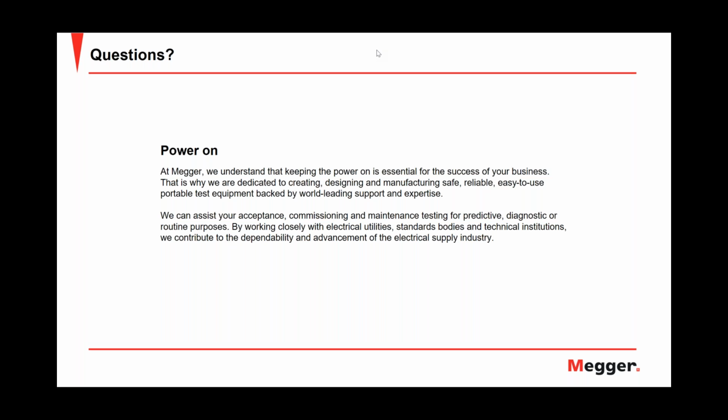And because you start at 0, you saw it in the demonstration when he said, what does a fault location situation look like? Let's say I take a smart thumper 16, you saw the needle going up, and then you saw breakdown at 1.6. So that was like 10 seconds. So it is not really a proof test.